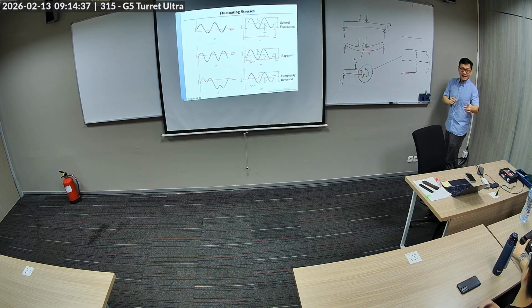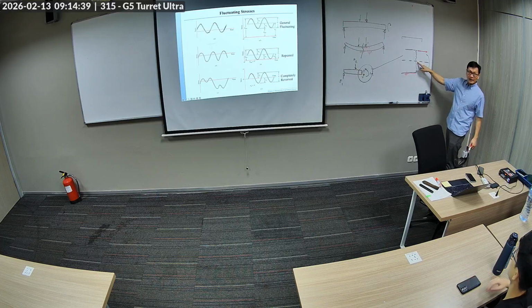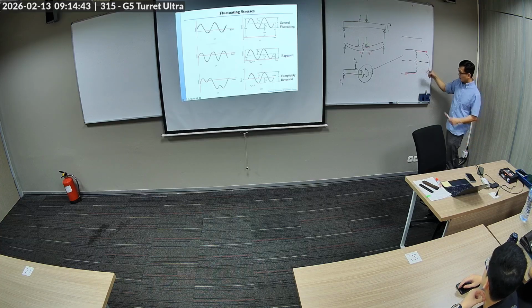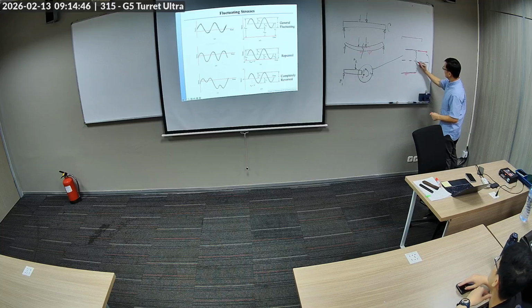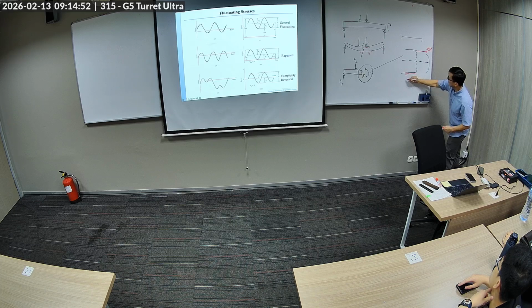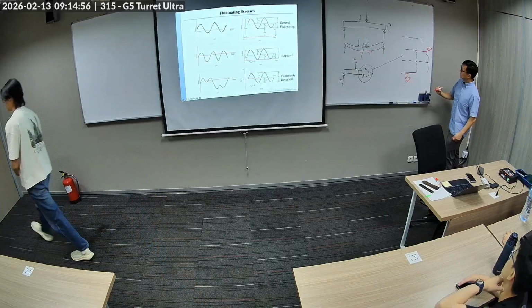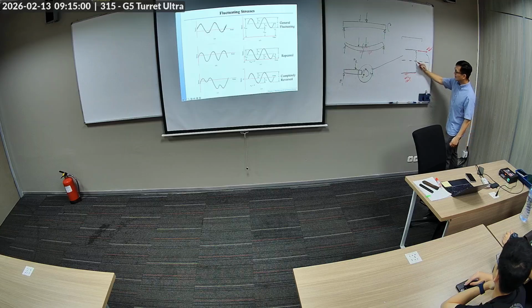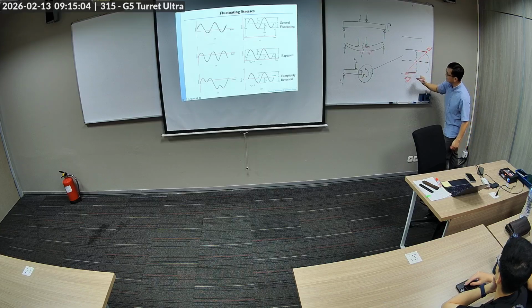It's a point where the stress is zero. Okay, we're getting somewhere. So it's zero here, it's maximum tension here, and it's maximum compression here. And the distribution somewhere in the middle is zero here, so it is decreasing like that.